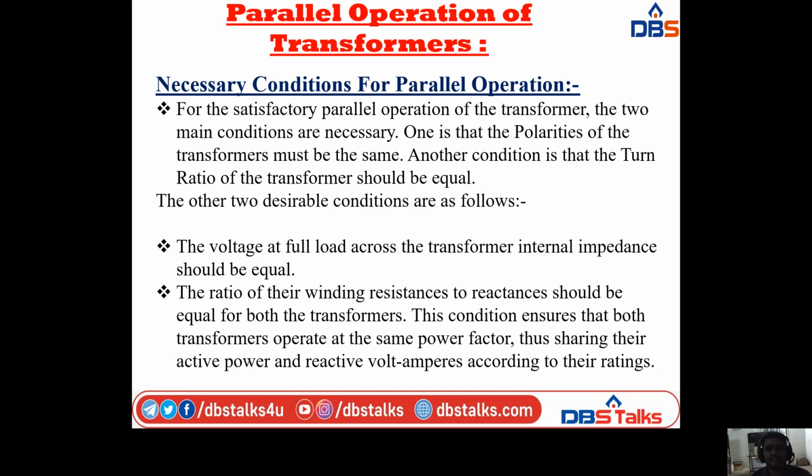The voltage at full load across the transformer, internal impedance should be equal. And next, the ratio of their winding resistances to reactances. So the ratio of resistance to reactances should be equal for both the transformers.